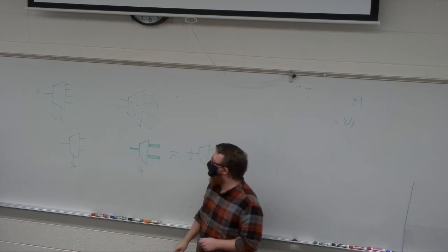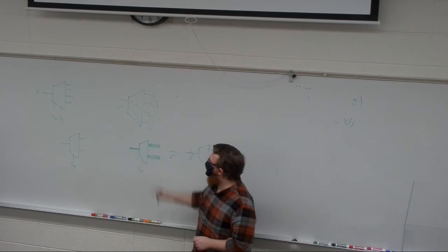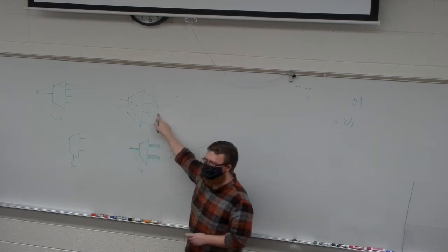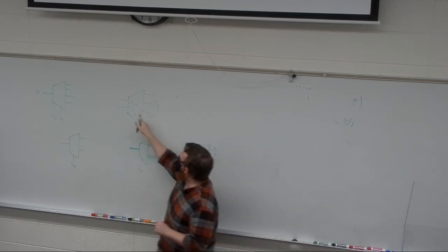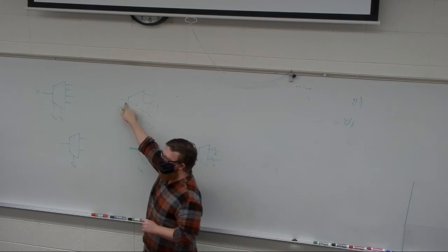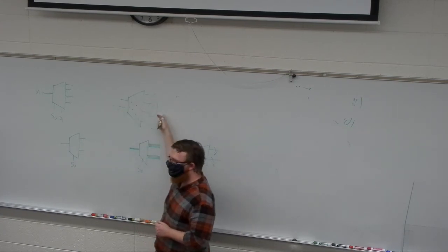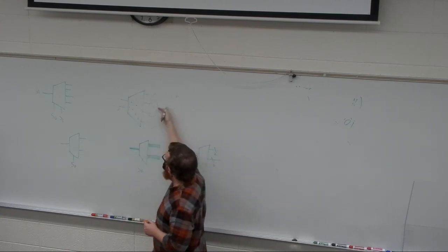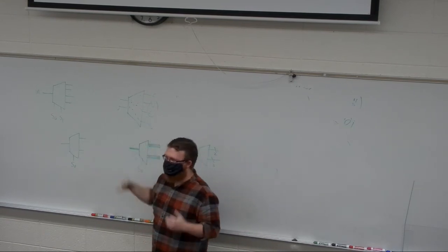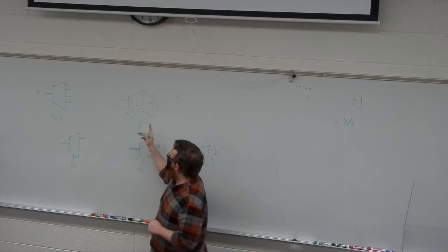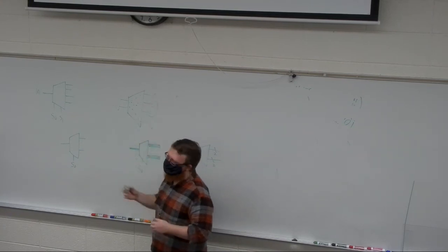Yeah, that helps. Because if I wanted to make this connection, then it's just two 1 to 3 muxes, because now there would be 3 locations, right? So this guy could connect to 1, 2, or 3. And then this guy could connect to 2, 3, or 4. And so I stick two 1 to 3 multiplexers, and now I can select that. But I need 2 select channels if I do that.